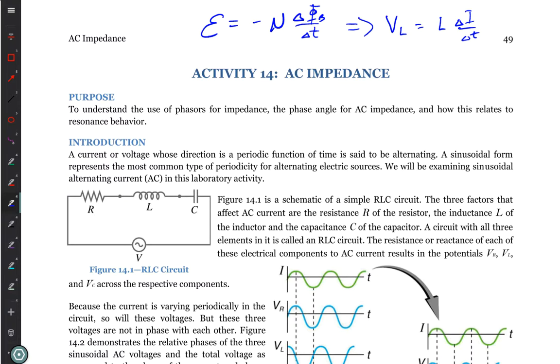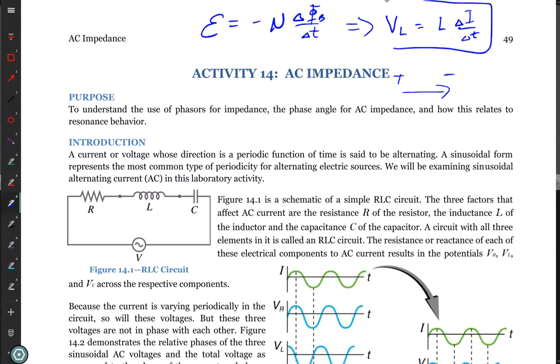It'd have to be negative inductances for everything if you kept that minus sign there. But the minus sign, we said, was only to remind us to look at Lenz's law for which direction the current's going to be. And so using our definition of if the current's going like this, then that's the plus and minus signs. We don't have the minus sign in this equation. And that's why I had the signs wrong, which one was leading, the voltage or the current. But they're out of phase.